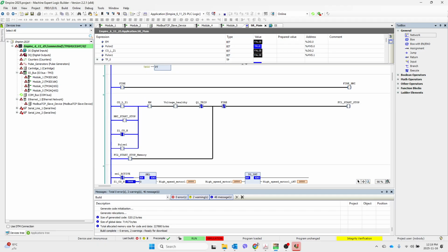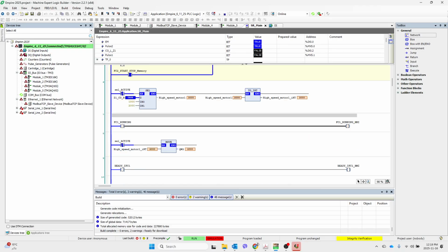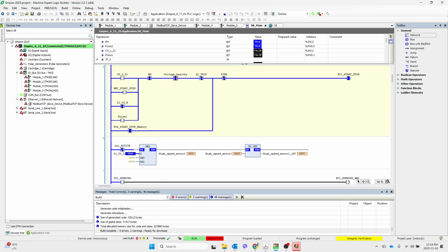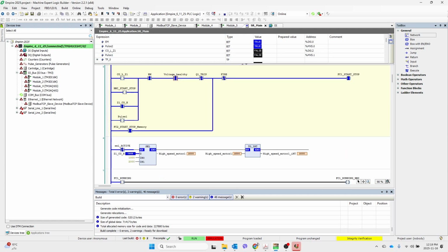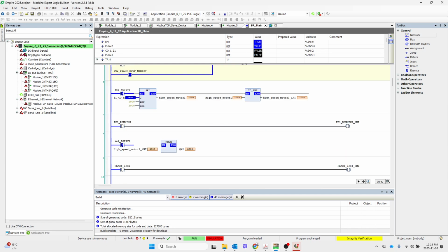So once I enable those also, if I don't have emergency, I have a voltage healthy, I will write those two indications also. I will give them FC start. Again, this contact is mandatory for the motor controller to start. Otherwise, it won't start without reference. Both those signals are mandatory for the frequency controller.